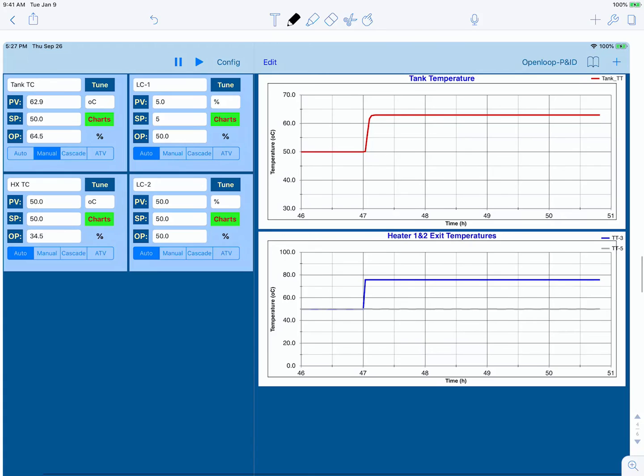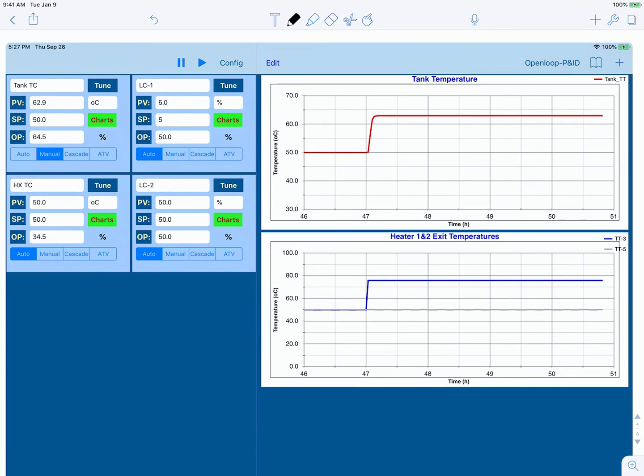The third response is one where we had a very small dead time and also had very little level in the tank, so we ended up with a very short time constant. The gain is the same as before, but the dead time to time constant ratio is now 0.05, which is the dead time, divided by, this is fairly easy to calculate, I'm not able to read it off the diagram, of course, but it's 0.018 time constant, and the ratio here is 2.7, larger than before.